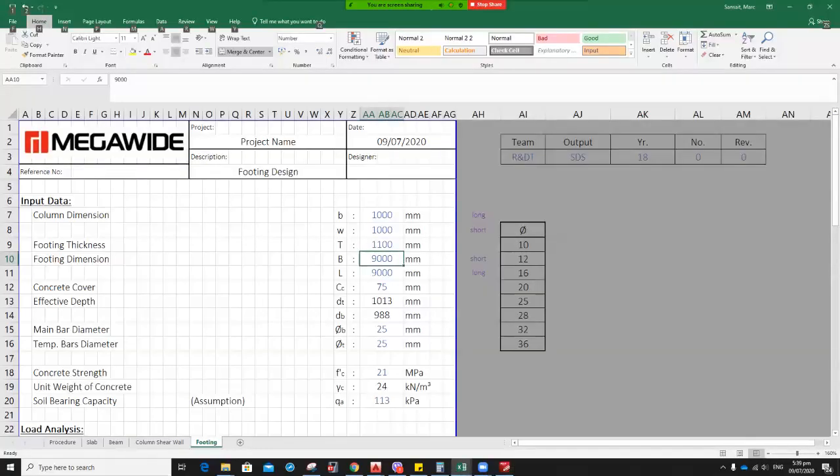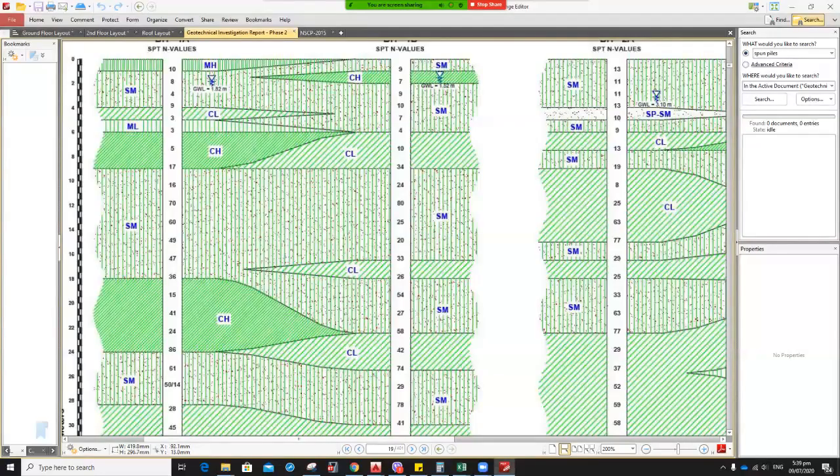Let's generate the first. But once we go to the SD1, we need to study if this foundation type is more economical than using piles. Maybe piles are already cheaper, especially bored piles wherein we can directly put the columns. Or maybe we can use push piles. Okay, so let's go back to the schematic.